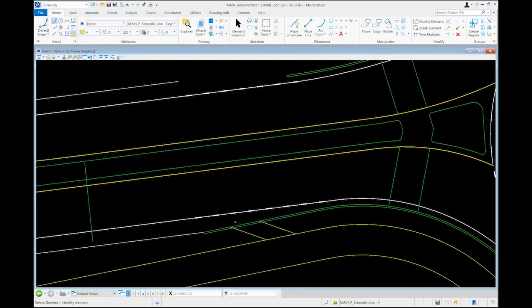They do still have to make a little bit of a movement to navigate up onto that ramp and up onto the multi-use path where there could be other pedestrians present. So we want to try to control that speed somewhat coming up, but still provide a smooth transition. So that gets us our ramp geometry up onto this shared use path.